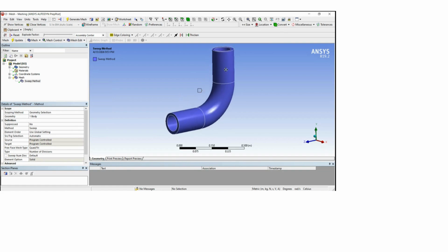These are all called side faces. So in step meshing, we need a source and we need a target. Once we start a mesh from the source, it will proceed and come out the same on the target face. Ansys has also given a good option in this part that we can select the source automatically, the target automatically, or you can select manual source and manual target.